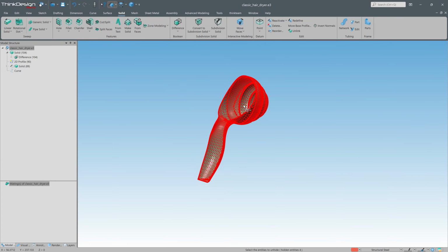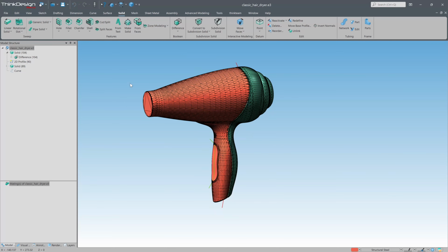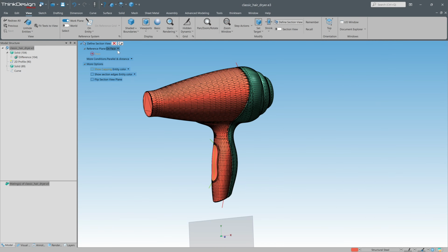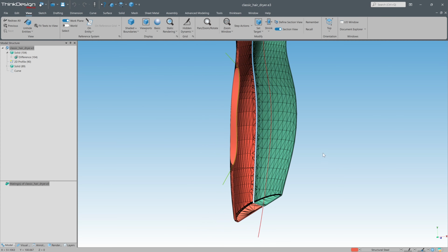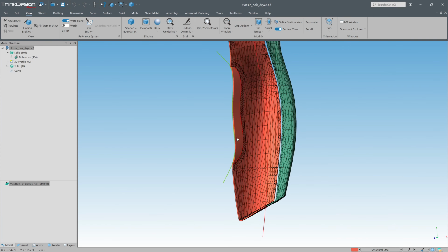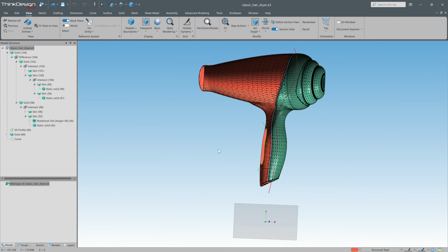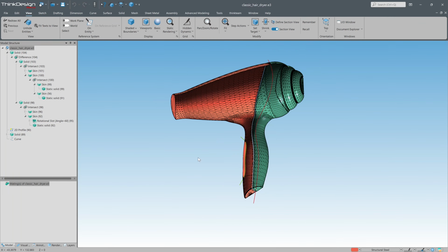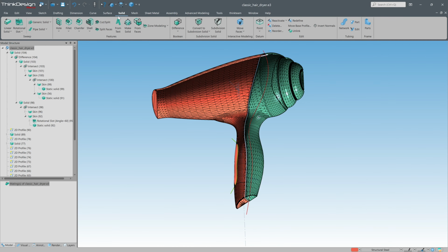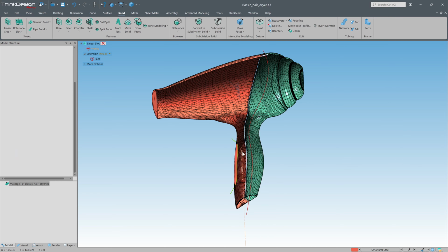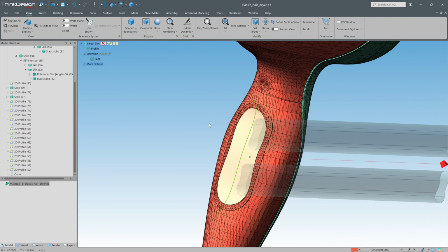The back cover is created using the same procedure. Apply the Define Section View command to section the model along the symmetrical plane. Launch the Linear Slot command, select the profile in the face, and apply it through the entire front part.